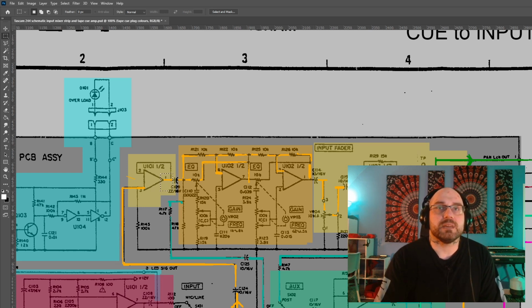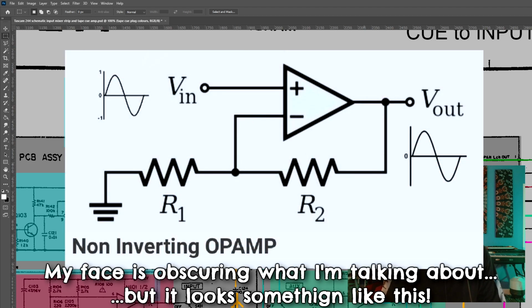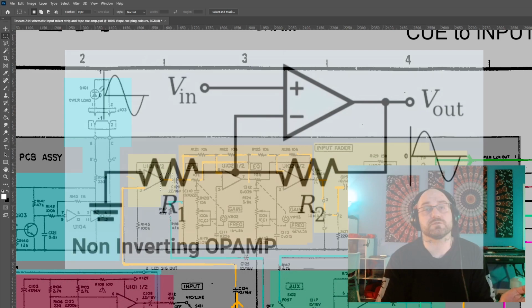But you make an amplifier out of them. It's got very, very high gain, so much high gain that actually it'll just completely saturate. That is, if it's got a 9-volt input, it can create signals that are 9 volts very easily, and therefore it doesn't amplify properly above that point. So we put a loop around them with components. Here you can see that there's a connection coming from the output, which is pin 1 there, through this resistor and being fed back into pin 2, and that controls the gain.